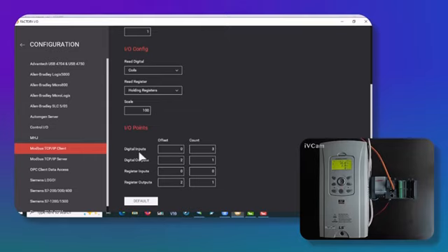Well, here I said I have 3 digital inputs. I have a start button, a stop button, and a sensor, the sensor that's at the end of the path on the common wire. I have a digital output. How many do you have? I say, I have 1 digital output, but I set it with an offset of 2.